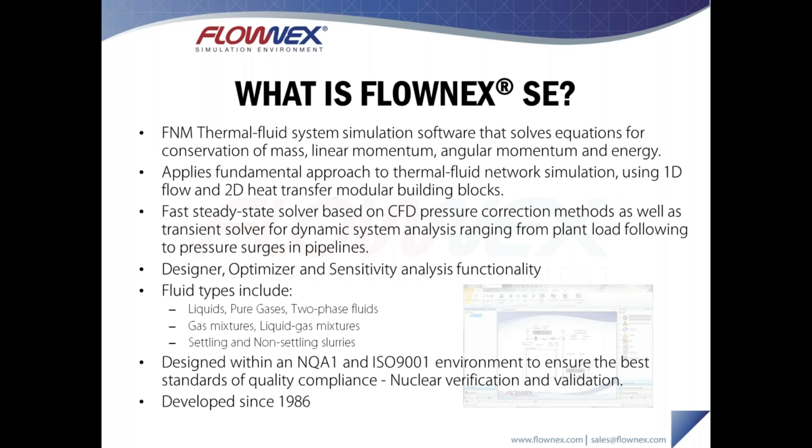So relatively large geometries or large sets of components. These models are done in both steady-state environments as well as dynamic or transient environments. The flow characteristics of the components are captured through empirical correlations, and the input data for these systems comes from process flow diagrams or component data sheets such as pump charts or turbine maps, as well as other network parameters.